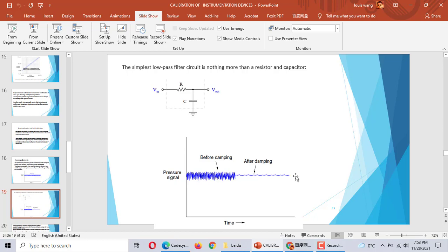All the metal cover should have the grounding line. But the grounding line was free, not connected, disconnected. We just connected it, and everything was gone. Okay, no noise. Everything was clean, so we just adjusted a little bit of damping. Okay.